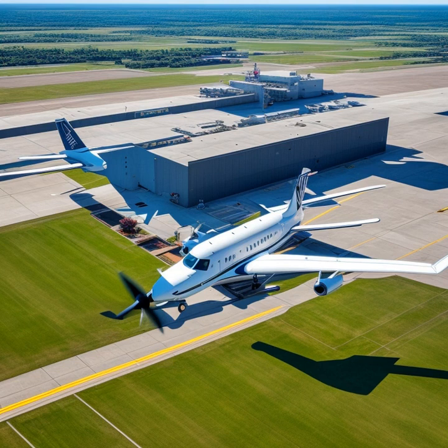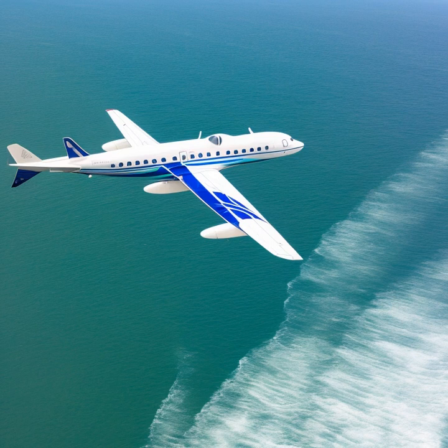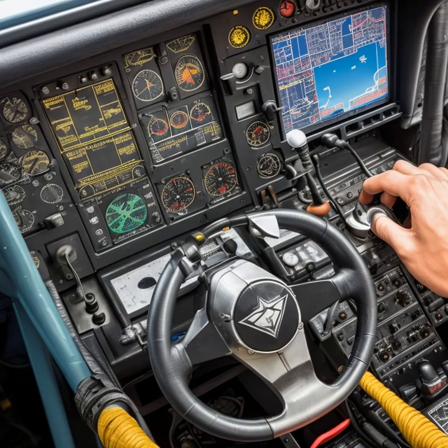Ailerons are located on the trailing edge of each wing and control the airplane's roll, which is the rotation around the aircraft's longitudinal axis, running from the nose to the tail. When a pilot moves the control stick or yoke left or right, one aileron moves up, while the other moves down. This changes the lift produced by each wing, causing one wing to rise and the other to lower, resulting in a rolling motion.